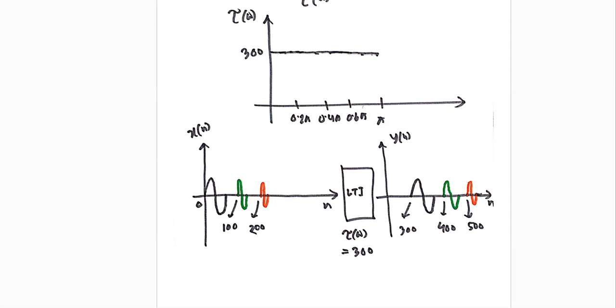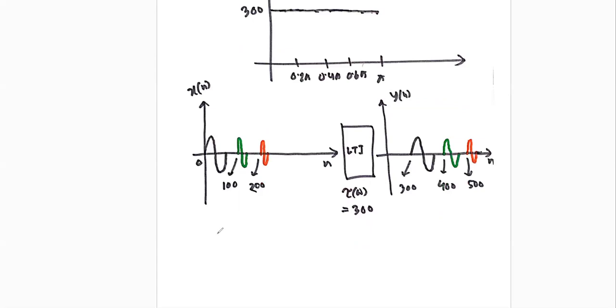Number one, you do not need to think about the group delay, because the phase response is linear. The phase response is linear. So this is all about the FIR filter, where the phase response is linear and our group delay is constant.